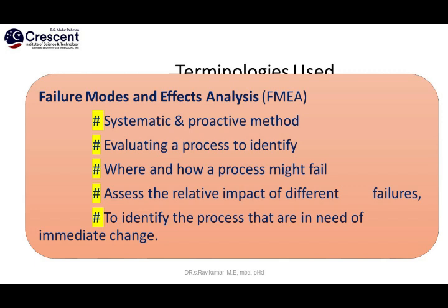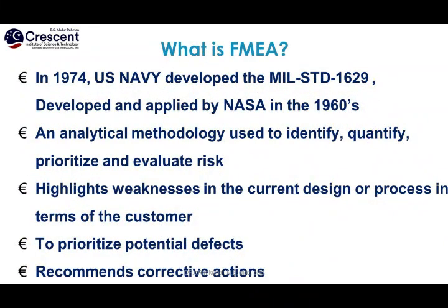Then what is process FMEA? See, if you are identifying a risk or potential failure modes in the existing system, in an ongoing system, and we rank the failures, prioritize them, evaluate them, and try to reduce their impact, that is called process FMEA. In subclassification, we can go for equipment FMEA, maintenance FMEA, service FMEA, and system FMEA. Those come under process FMEA by default. So these are the two main classifications of FMEA which we must know: design as well as process.